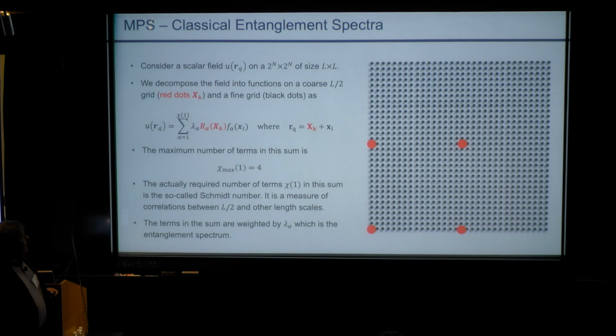So what we do is, if we have a grid, like this two-dimensional grid, and we want to represent the flow field on it, I pick out the largest length scales, and I pick out the 4 grid points here. This lower grid point would describe this part of the grid, this grid point here would describe this part, and so on.